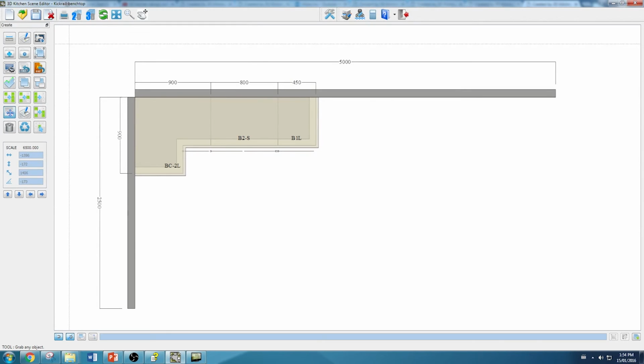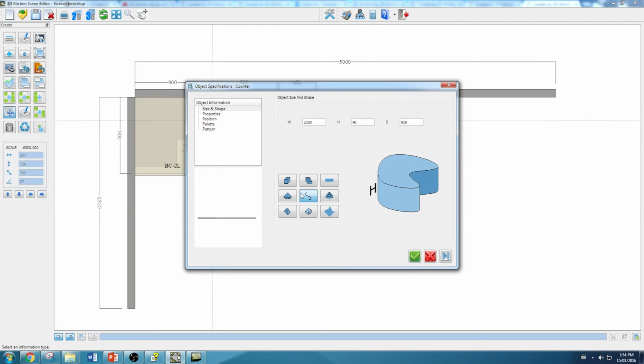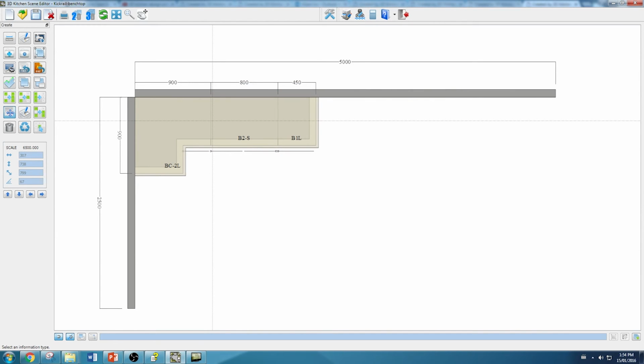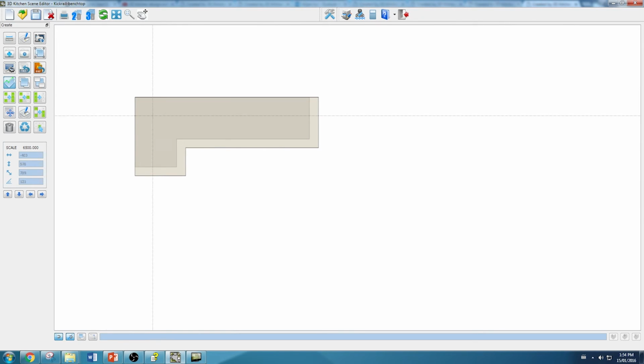Creating curved surfaces on benches. After the bench is already drawn, click it with the right mouse button, click the Bezier icon, click OK. Click the polygon editing icon, click on the bench. This places squares all around the corners. Click the square at the right hand end of the side you want to create an arc for.